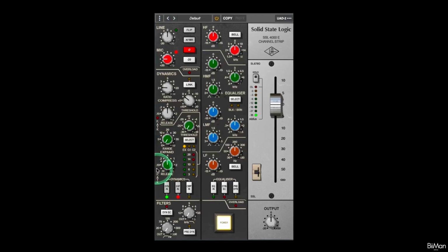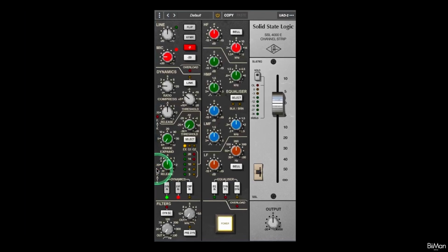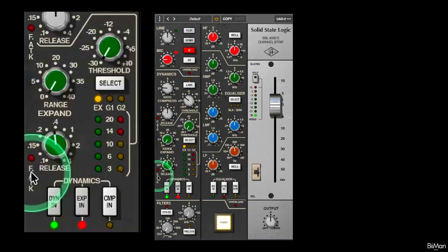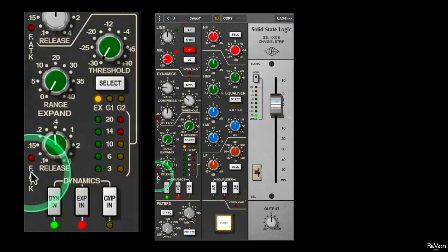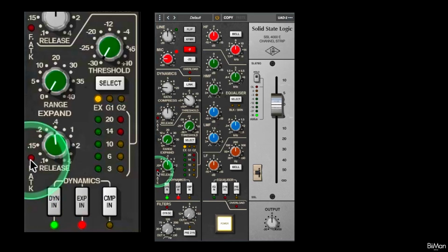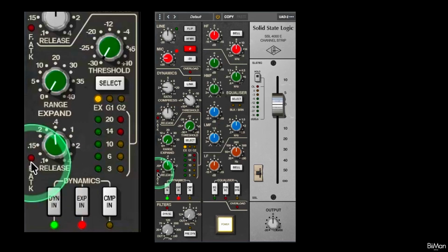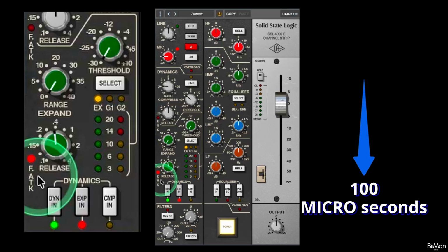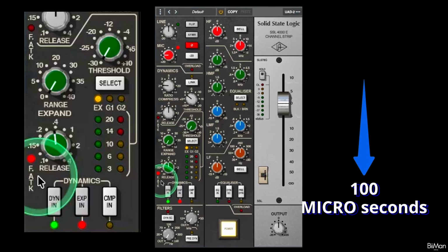This lets the gate expander module set the duration between the input signal reaching the threshold and the end of dynamic processing. Expansion gate attack time is fixed at 1.5 milliseconds per 40 dB of gain reduction when this switch is not engaged. When engaged, the attack time is fixed at 100 milliseconds per 40 dB of gain reduction.